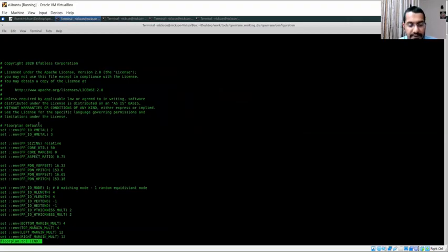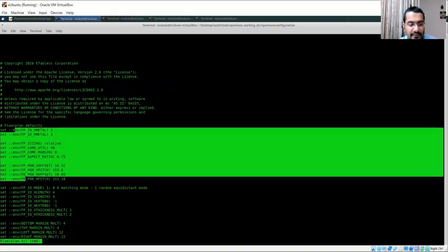So these are basically the default parameters which are set for the floor plan stage in OpenLane. See this, this is how you'd set it. Set, and this is the environment variable, and this is the variable name, the switch name. So this is setting all those values. This all we have seen.